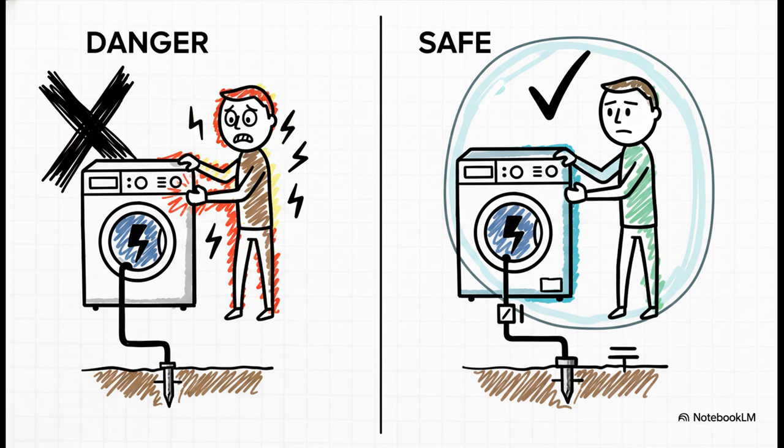But here is a strict warning for you as future engineering peers. When that hybrid inverter decouples from the commercial grid, you lose the utility's centralized neutral earth reference point. And if there's a short circuit to a metal appliance chassis while you're running in isolated backup mode, the fault current will have no return path. Your overcurrent breakers will simply not trip, leaving an exposed metal frame energized at lethal voltage.